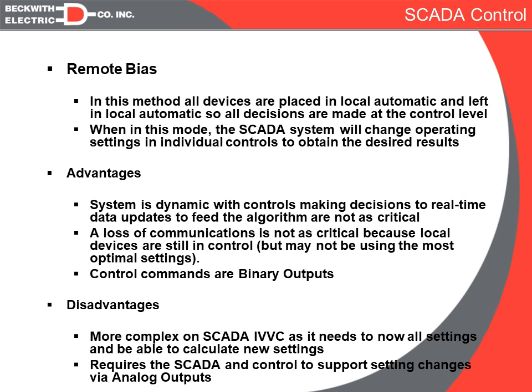The disadvantage to this type of system is it is more complex on the IVVC software. It's much easier to say close than it is to calculate the settings, to know what the settings are in that control, and then to calculate and know what you need to change them to in order to get that control to decide on its own to close.